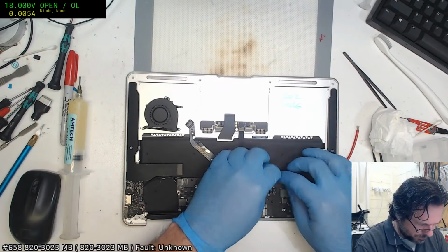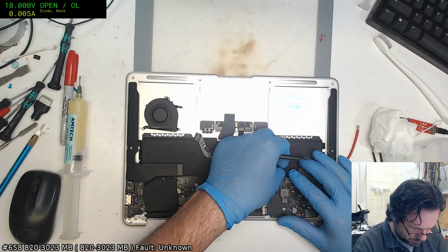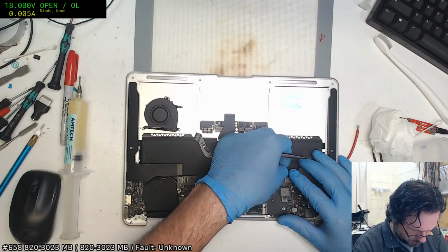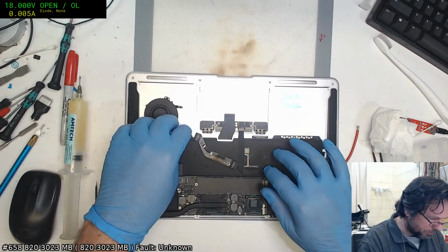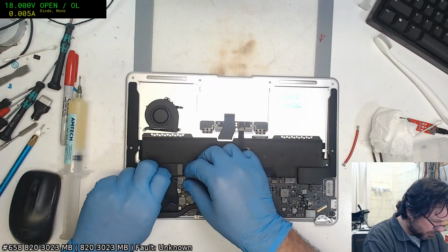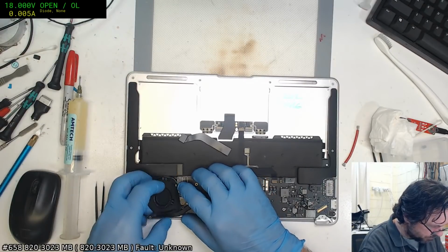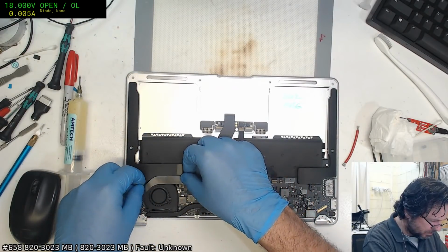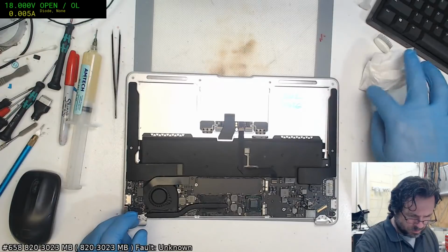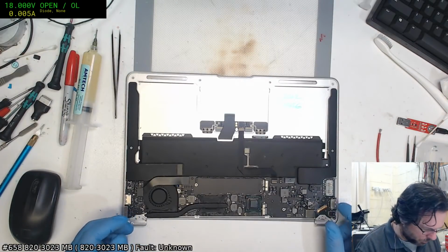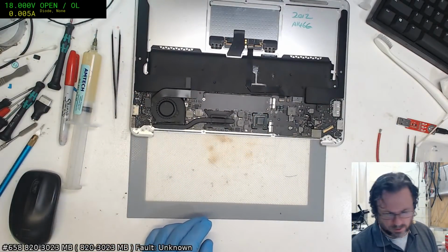Yummy steak there. No, you might have been looking at the other test pad. There was one that most certainly did have a via in it. The one I just fixed up did, because I scratched it right back, took the surface layer of copper off, and right in the middle of the pad area was a chunky little via going down into the board. But there were multiple test pads I was working on there, so that's why you're probably a bit confused. But that's okay, I understand.